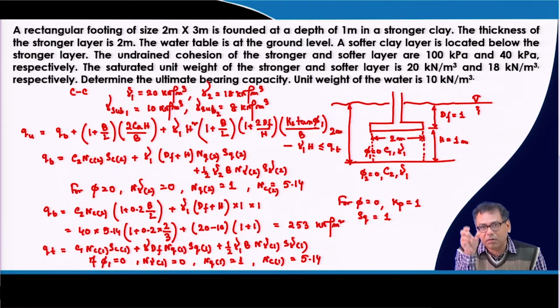That means all the stresses act on the bottom layer within the same width as the width of the foundation. You can question that when you apply the load the stresses will be distributed, so the loading area on the second layer may be more.